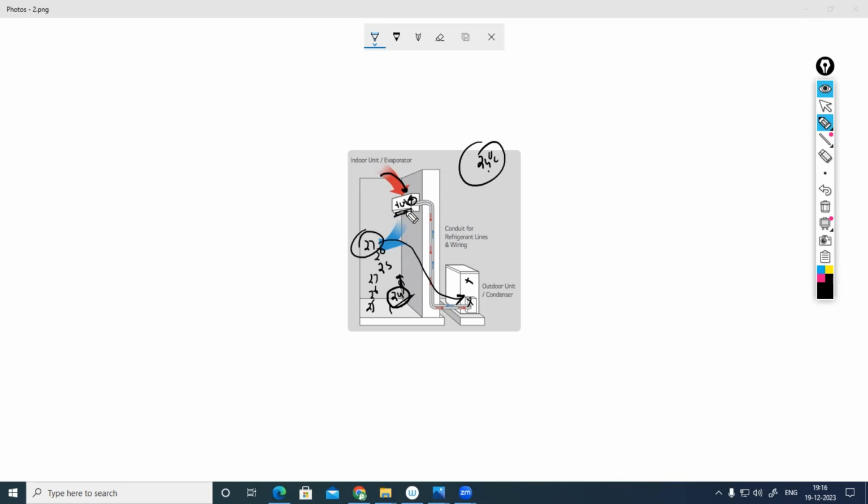I will explain. So that's why, even if the compressor and the condenser fan are not working, once the room temperature has achieved 24 degrees Celsius, your blower fan should work. Not at high speed, because most indoor equipment now can be adjusted with a minimum of 3 speeds. Speed number 1, 2, 3, right? Sometimes there might be automatic machines. With bigger machines it will automatically decrease. In split AC and all, we do not have that provision, but big machines will automatically decrease the fan RPM.